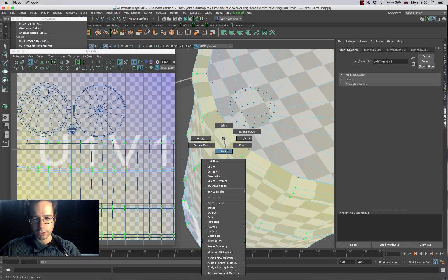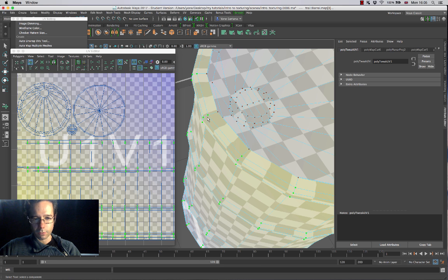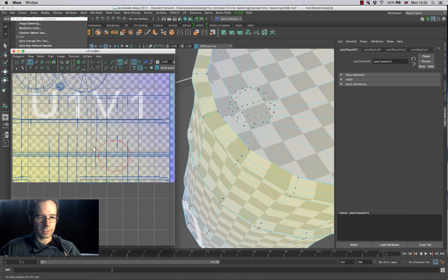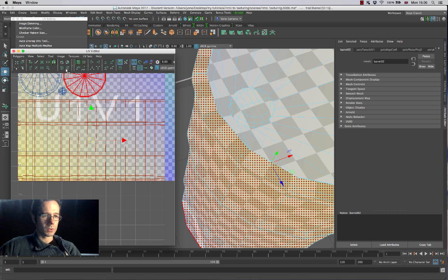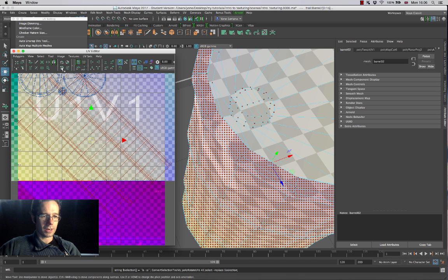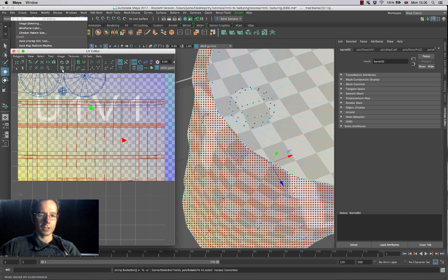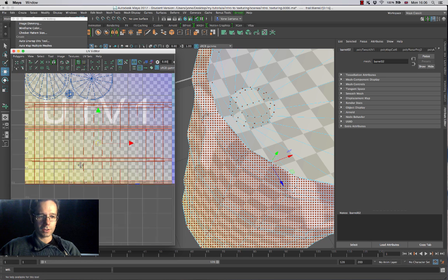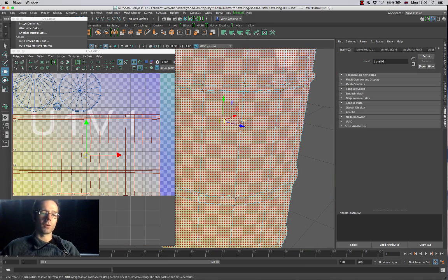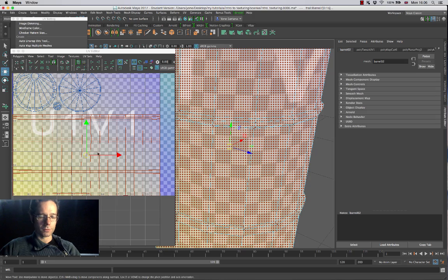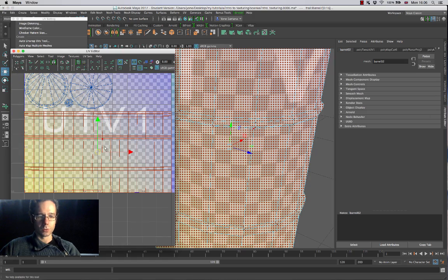And if I really needed to go into very fine detail as well, I can go into the UVs over here and just figure out where these UVs specifically are. They're over here. Actually, I should have this object probably inverted. So I'm going to come over here and switch to my Move tool, come into my shell selection mode, and select all of this. I'm going to use some of these tools over here to quickly rotate this around 180 degrees. This is like 40-degree increments as it goes up, just so that I've got these UVs in a slightly more organized place. So again, depending on what I'm looking for, I might have to use more of this tool or less of this tool as I see necessary.